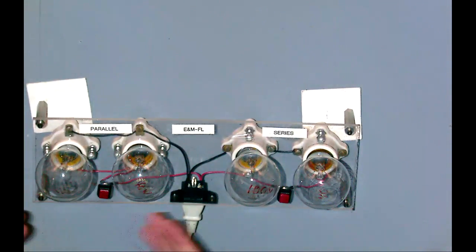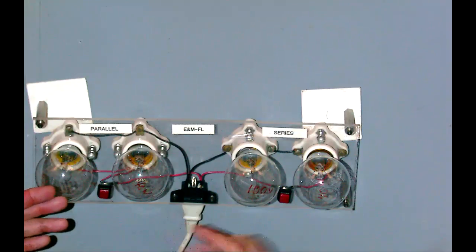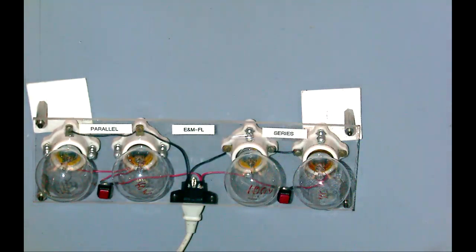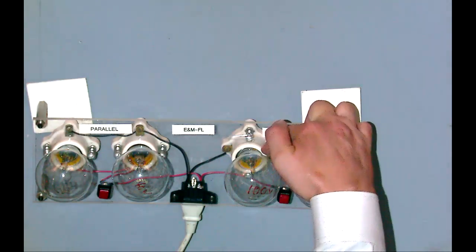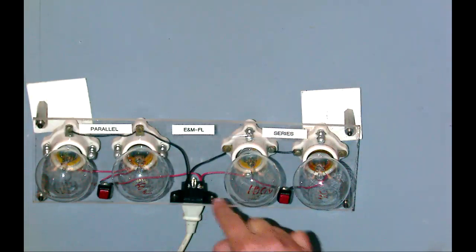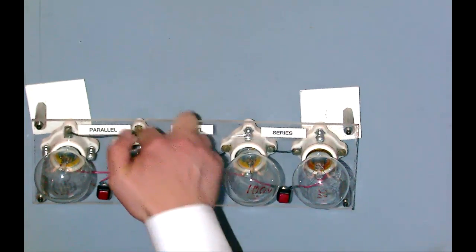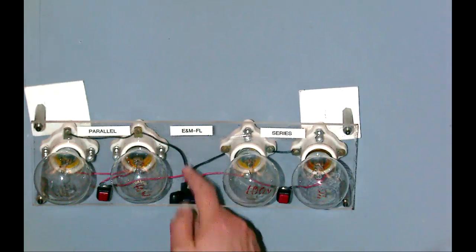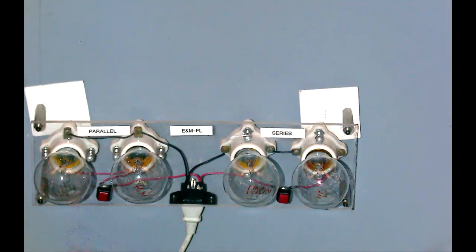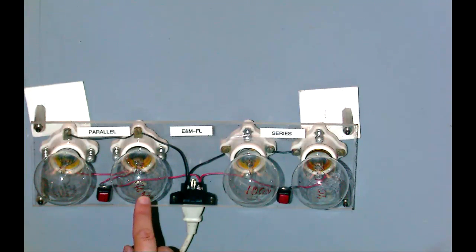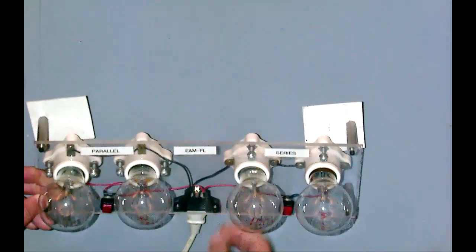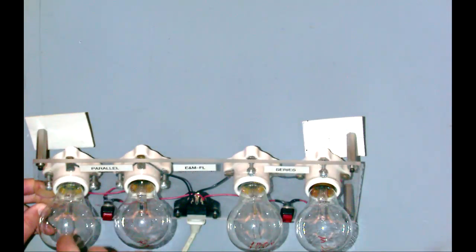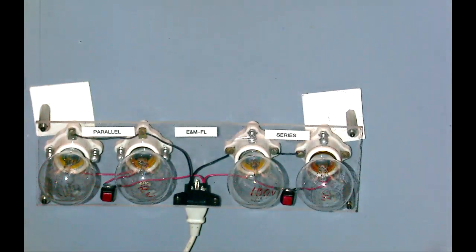So how do I know which bulbs are connected in series and in parallel? I can read. But also I can see wires. Yeah. So there's a wire, then a second wire from the first bulb to the second, and go back in series. And here I have wire and wire, positive to positive, well, actually negative to negative, and here positive to positive, in parallel. So these two bulbs have different nominal. This is a 40-watt bulb, this is a 100-watt bulb. You actually can see they have slightly different filament. This is a straight one, and this is like a semicircle.